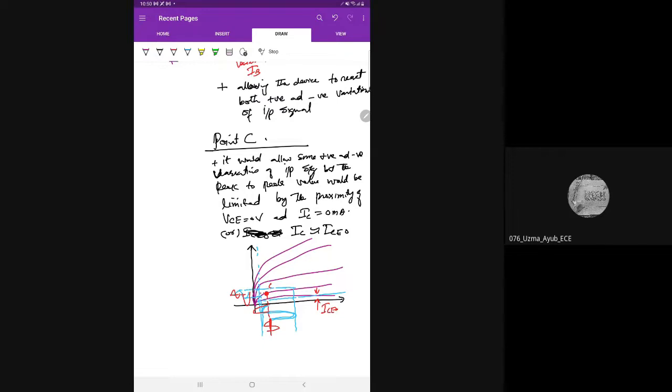तो यहाँ अगर हमें करना है, काफी ज्यादा ध्यान रखना है इस पॉइंट पे, बहुत ही कंट्रोल ऑपरेशन करना है, बहुत ही कुछ ही डिफाइंड वेरिएशंस हमें अलाउ करनी है इनपुट सिग्नल में। अगर रैंडमली उसने क्रॉस किया इनपुट सिग्नल में, it crosses beyond that range, then the BJT may be driven into saturation or it may be driven even into cutoff region. ठीक है?